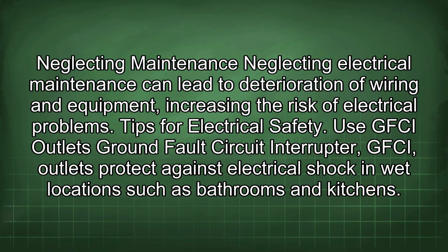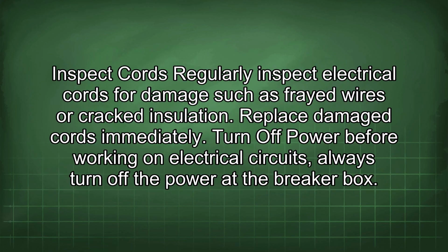Tips for electrical safety. Use GFCI outlets. Ground fault circuit interrupter. GFCI outlets protect against electrical shock in wet locations such as bathrooms and kitchens. Inspect cords regularly. Inspect electrical cords for damage such as frayed wires or cracked insulation. Replace damaged cords immediately. Turn off power before working on electrical circuits. Always turn off the power at the breaker box.